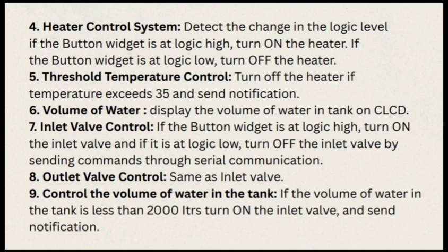Seventh one is inlet valve control. The inlet valve is operated using a button in the GUI. In simulation, if the logic is high, then it opens the valve. If the logic is low, then it closes the valve. Commands are sent via virtual serial communication.